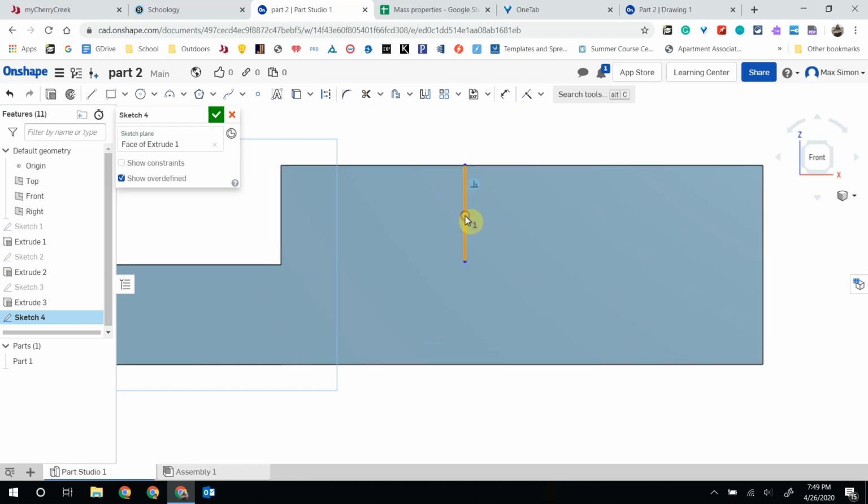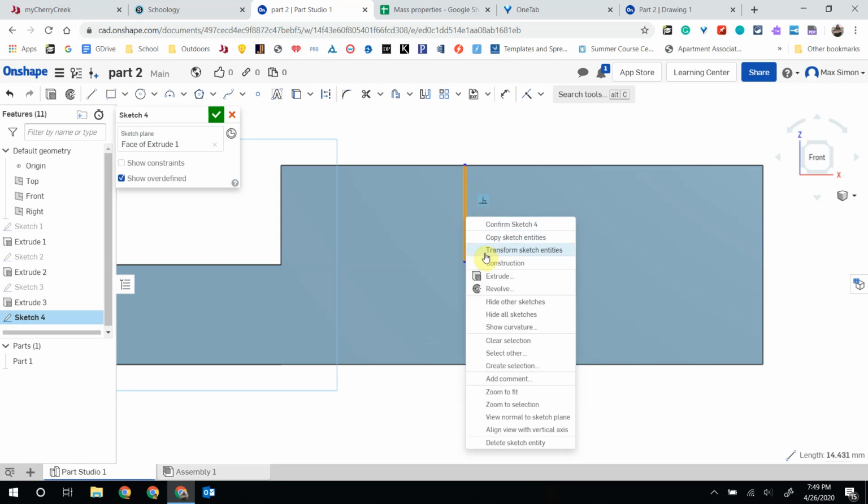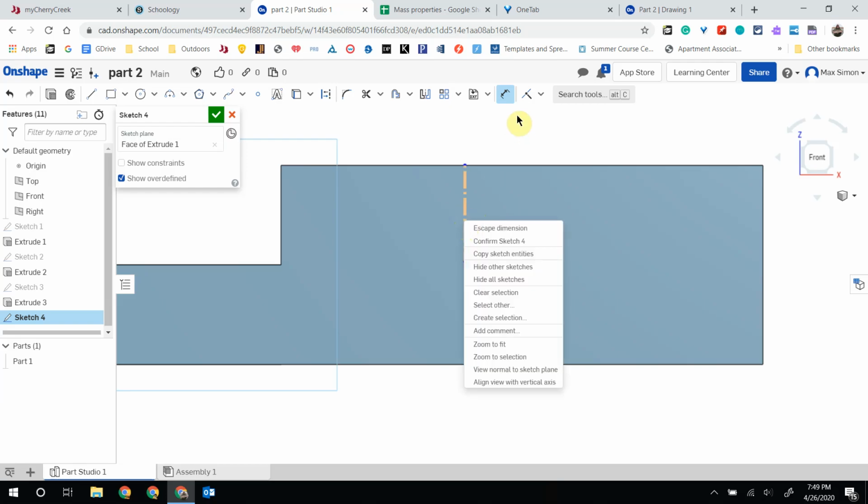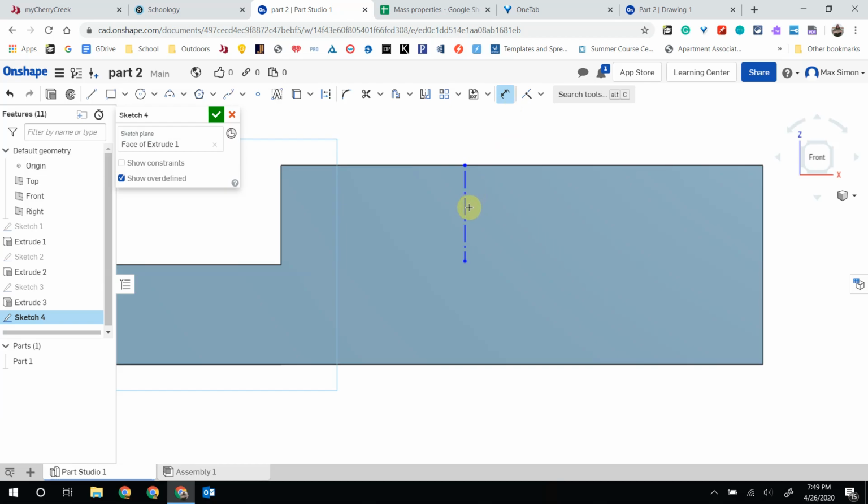So sorry, cutting that line out. Deselect that trim tool, take this line, and when I get out of the line I can come back into it and I'm turning that line on for construction. Now, a line for construction means that line isn't actually going to be extruded, it's just a frame of reference. So now that we have our dimension tool turned on, let's take this line and dimension it from here to here.